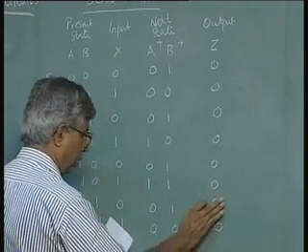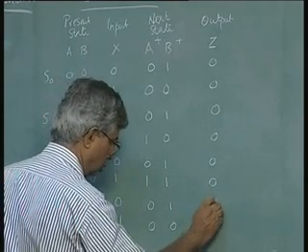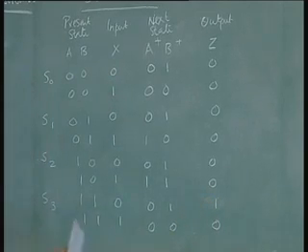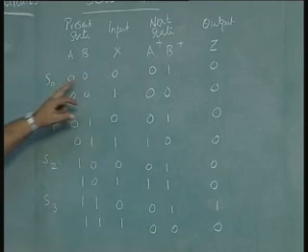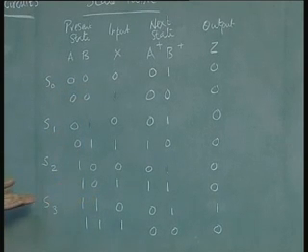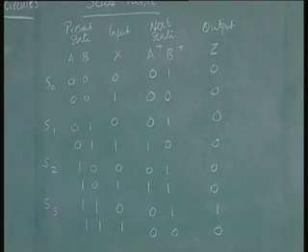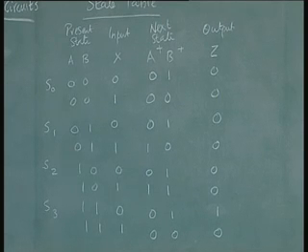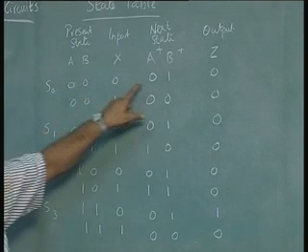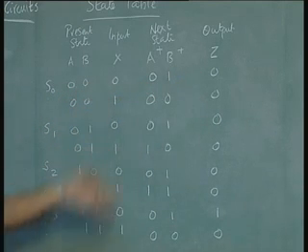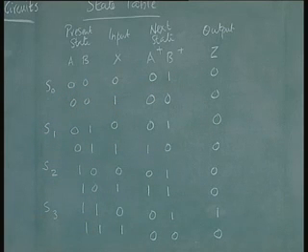Oh, this is a 1, output is a 1. This is the next state table, next state and the output information corresponding to the present state and input. This is the same table which you got last time, or you can also simply get it from here. For example, if your state is 0 and input is 0, output is also 0, and the state goes to 0 1. So, 0 0 0, 0 1, output 0. Like that you can do all the 8 rows.